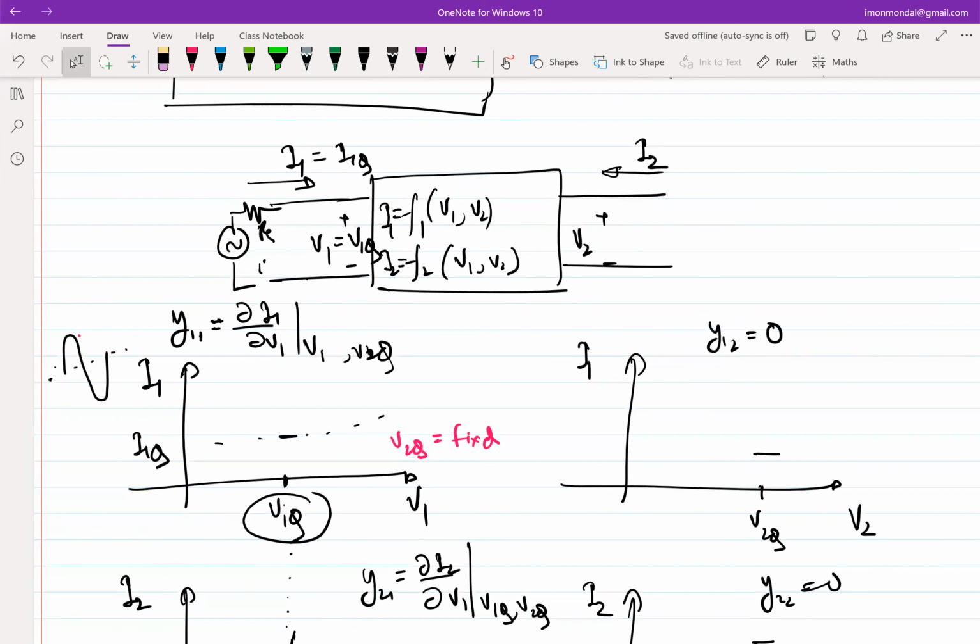then can you comment on when the input is swinging? When the input is swinging, can you comment whether V1 is held constant or V1 is also swinging? Is it? I mean, in the presence of input VI, is V1 held constant or is it changing? It's changing. If it is constant, then you will not see any change in I1 or V1, right? Which means you will not see any change at the output also. It's equivalent to saying I have a fixed battery, I have connected it there. Whatever happens in the rest of the universe, the voltage will not change, right?